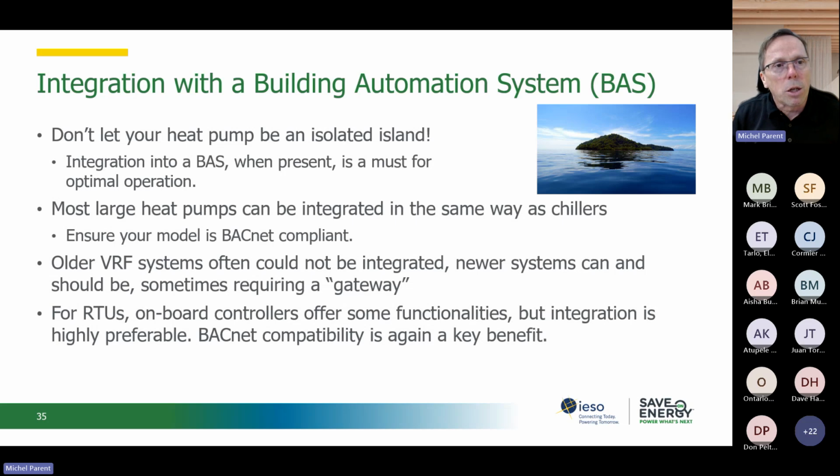I talked about integration with the building automation system. You do not want your heat pumps to be this isolated island that works on its own, even for rooftop units. If at all possible, obviously, if you have a BAS, you want something that is BACnet compliant, so you can connect to that heat pump and you can control when it's going to work and when it's going to go to, let's say, natural gas backup or any other backup, to properly manage your demand, because that's where the heat pump can get you, if you don't manage the demand properly.